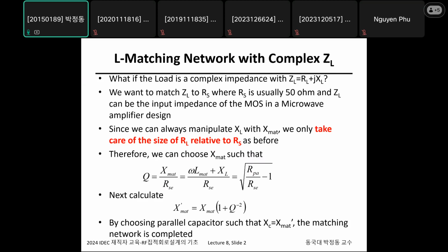center frequency divided by bandwidth. That is actually 1 over fractional bandwidth, as we learned last week, right? So the ratio between source and input resistance determines quality factor Q, which means it determines bandwidth and it determines insertion loss, right? So that means the reactance part is actually easy to control, right?